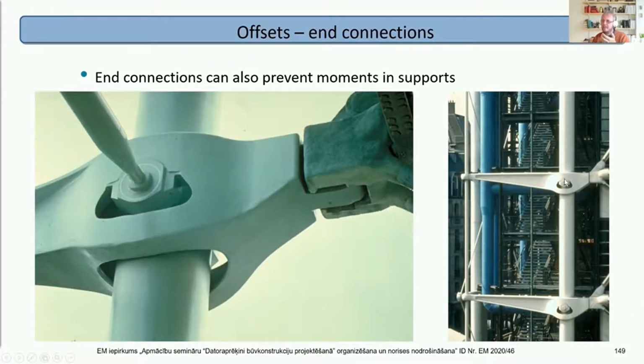What you do then get is shear force here, the cantilever and tie rods at the outside. So the moment becomes this lever arm. Probably not worthwhile doing for all projects, but for the Pompidou Center, it was quite an interesting expression of structural mechanics.